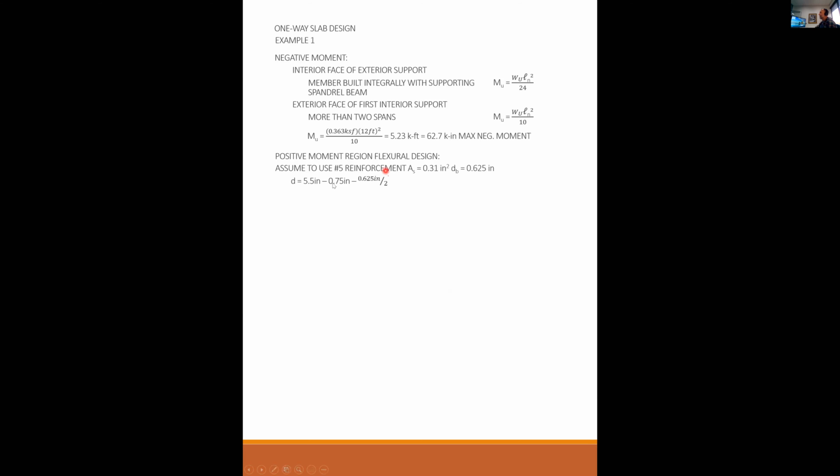One-way slabs, we actually calculate what D is. D is the thickness of the slab minus the coverage minus half of your bar. And I get to 4.44 inches. I use my Rn factor, Mu over B D squared. In this case, I know everything. I know my moment. I know my B is always going to be 12 for a one-way slab. And my D I just calculated is 4.44. So I get 210 psi. From the table, I can find it quicker from the table.